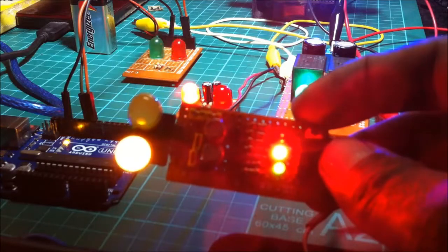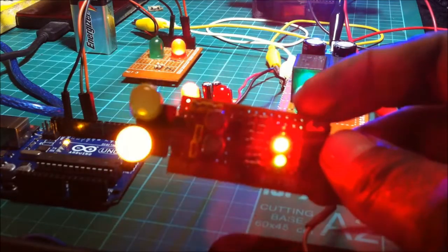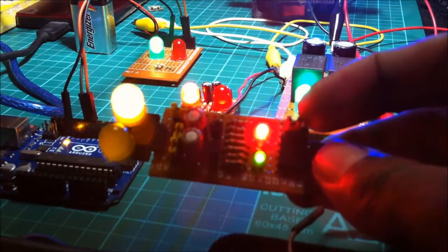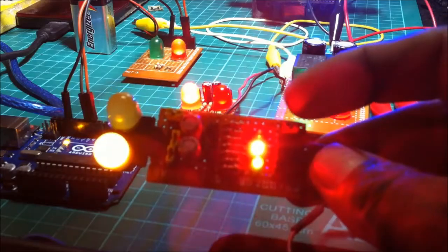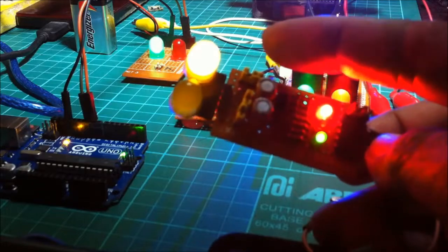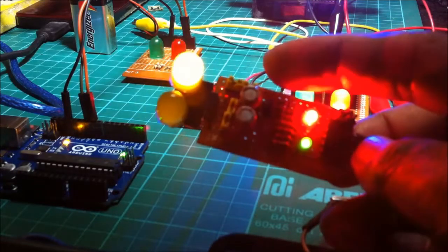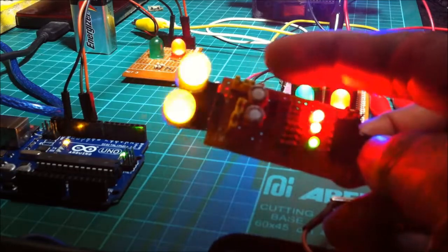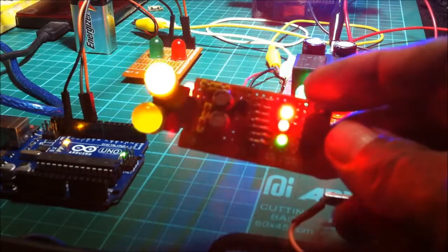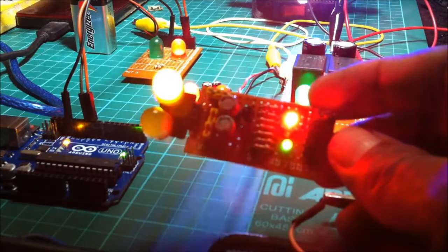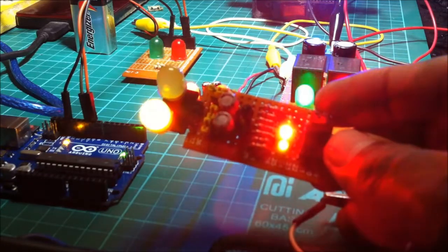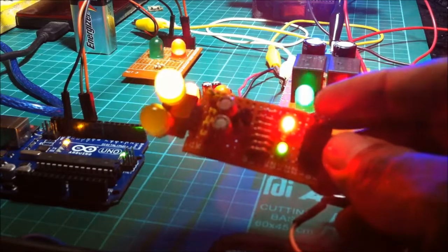We can use this as an oscillator circuit for any circuit and as a clock that provides this oscillation, the alternating, blinking, flashing of the LED. We can use 9 volts or 5 volts by changing the jumper settings. We can use one LED or one output of this multivibrator by changing this jumper settings, either left or right. So it has multiple uses.